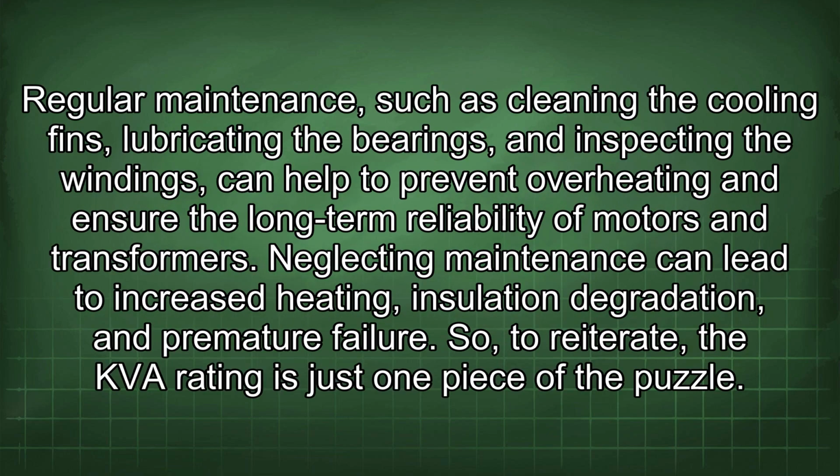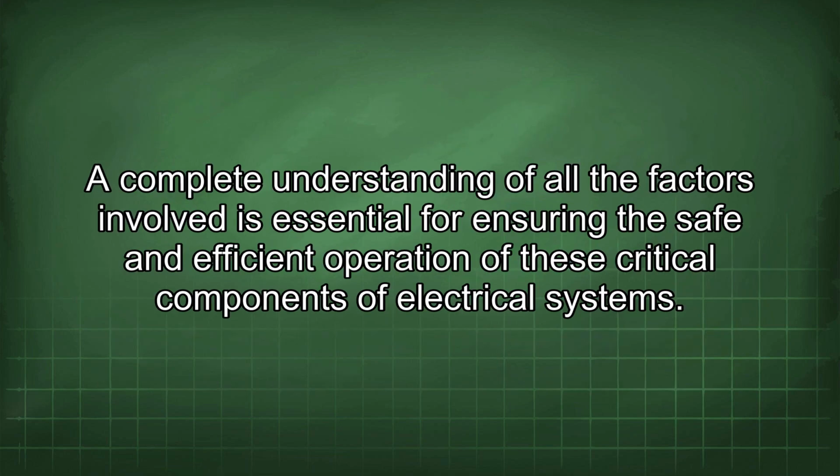Regular maintenance, such as cleaning the cooling fins, lubricating the bearings, and inspecting the windings, can help to prevent overheating and ensure the long-term reliability of motors and transformers. Neglecting maintenance can lead to increased heating, insulation degradation, and premature failure. So, to reiterate, the KVA rating is just one piece of the puzzle. A complete understanding of all the factors involved is essential for ensuring the safe and efficient operation of these critical components of electrical systems.